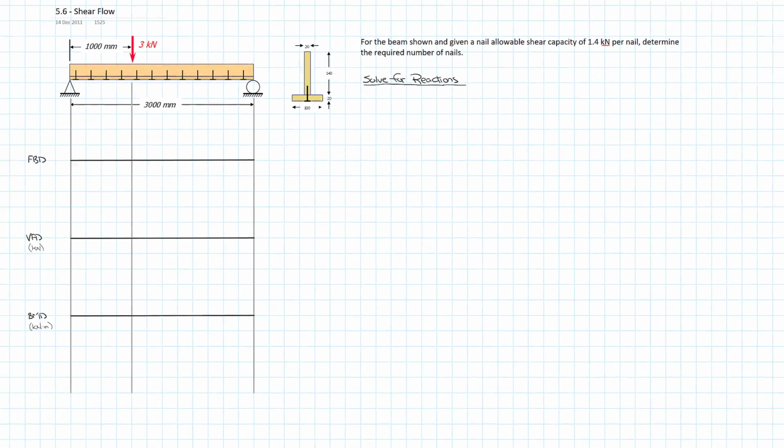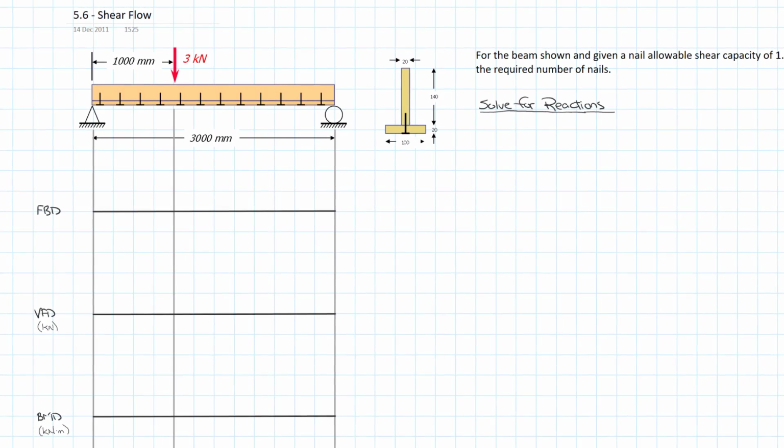So the first step, inevitably, free body diagram, use our static equations to solve for reactions. So let's get the free body diagram drawn in. So pin end at A. Oh, so we don't have labels. So let's label these A, and we're going to call the point of load application B, and C over at the far end. And now we're ready for our free body diagram.